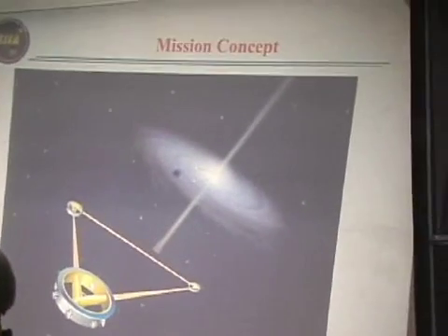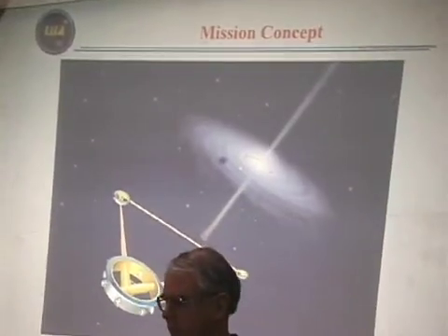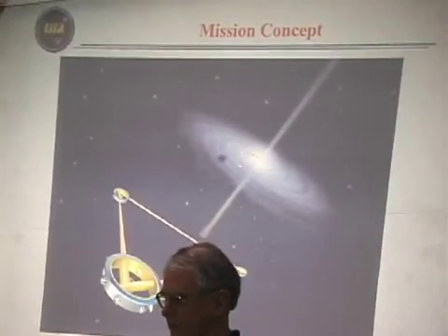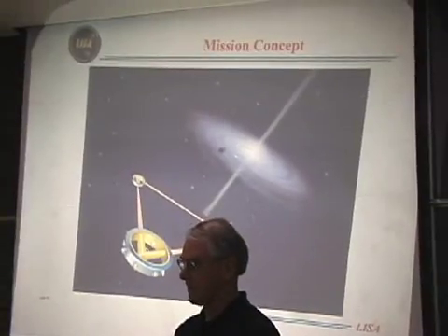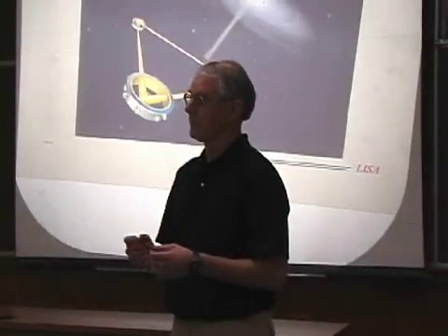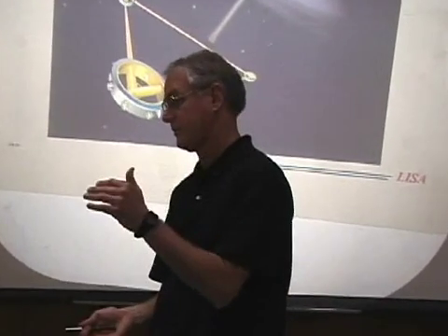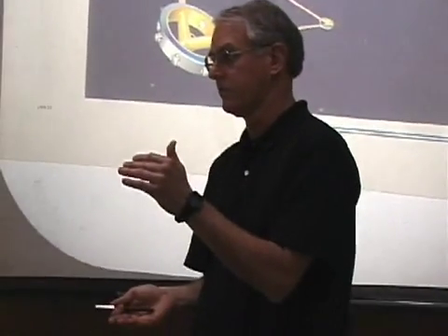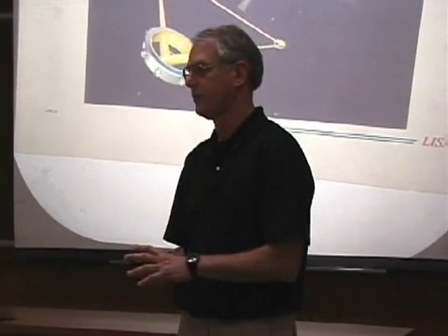Okay. So the pretty picture. You'll define the y variable. Y is delta F over F. It's the change in frequency divided by the center frequency. It's favored by the frequency and timing community because the so-called Allan deviation of delta F over F is a characteristic of how good an oscillator is. And this, in my opinion, is a nice way to discuss, in a consistent way, the noises of a bunch of apparently disparate noise sources. And so that's why all of what I'm talking about today, I'll convert into that mode.